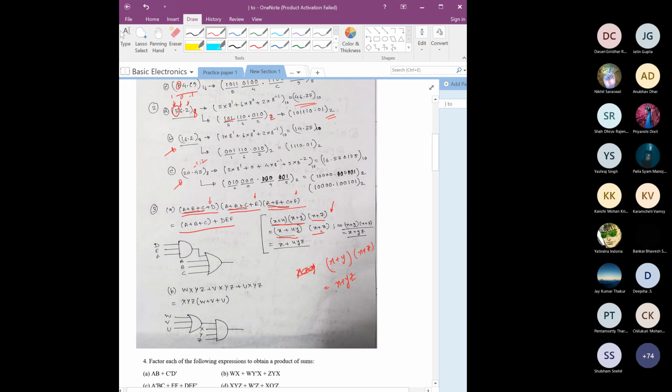Then if you take these two and apply the same formula again here, you will also get this, right? Once the Boolean function has been represented in this fashion, you can see we need only one OR gate and one AND gate to make this. Because D E F is a three input AND gate, and that is this function. Then we have taken this one, and we have used a four input OR gate, because no restriction was given on the maximum number of inputs for each gate.